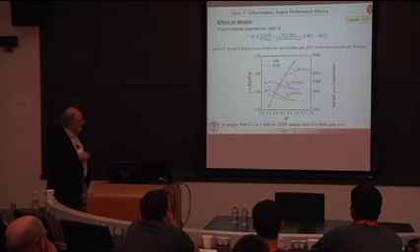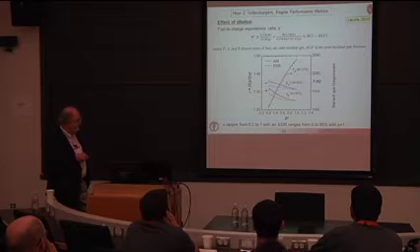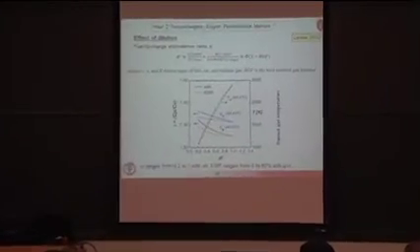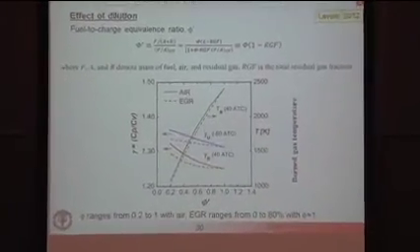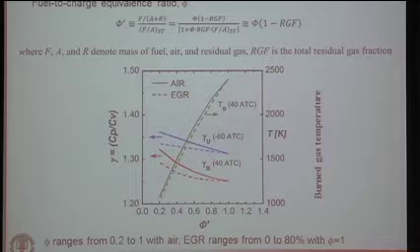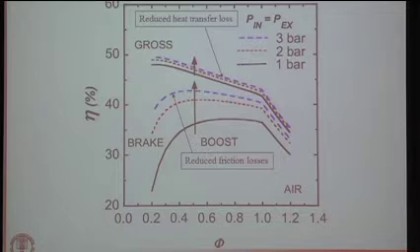Interesting that if you look at the predicted burn gas temperature, someone was asking about these earlier, you see burn gas temperatures for these lean mixtures are very low, 1,000 Kelvin, and going up to on the order of 2,500 Kelvin for stoichiometric mixtures. But the differences are not that large if you have air or EGR dilution. And part of that has to do with the gammas here for the air and the EGR dilution for the unburnt and the burnt gases. So that's an interesting result from the analysis.